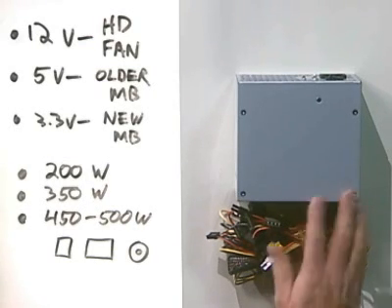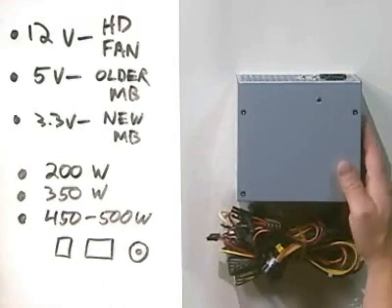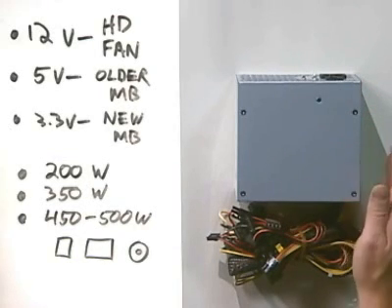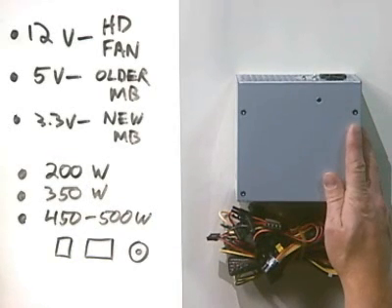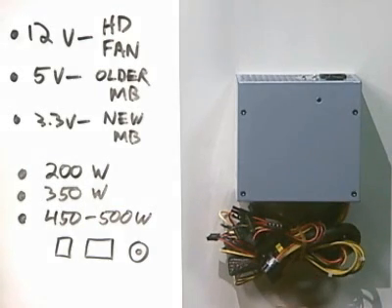It can also be caused, even though your power supply has plenty of wattage, if you've blocked air ducts and you don't have good ventilation around the system, this power supply can get too hot. When that happens, it gets overstressed, and the same thing can happen again. You lose power on the power good wire.